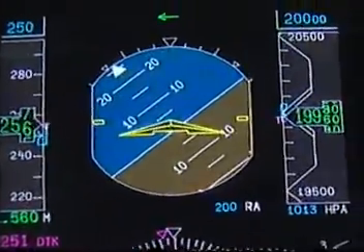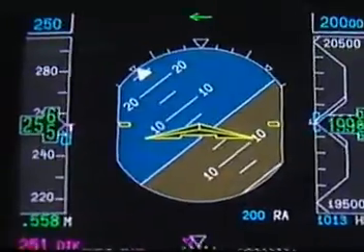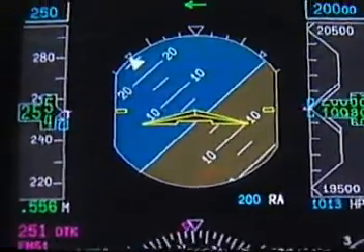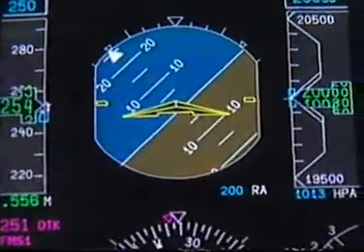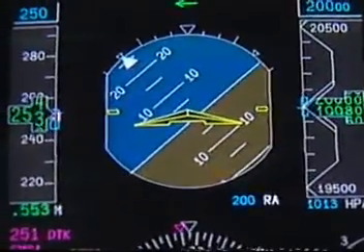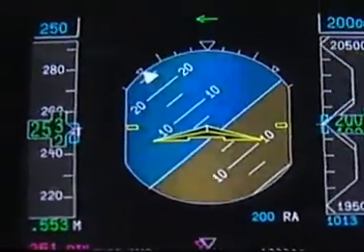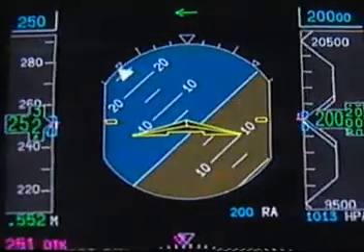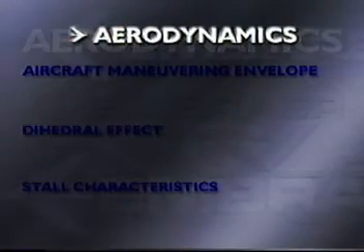The unwise pilot may not recognize he is flying in the low-speed side of the envelope and incorrectly add power to speed up the airplane. Such an error will actually not help and will make the situation worse. Some care is necessary to know the maneuver margins, and for good reasons. Take a look at the buffet onset envelope in your AFM. Get the low speed and high speed margins, and fly always in a speed coherent with those margins.